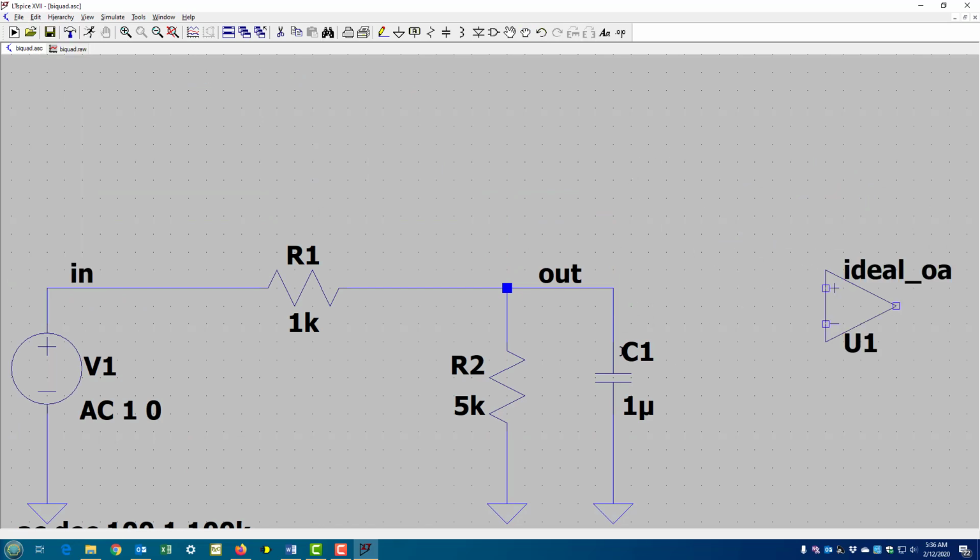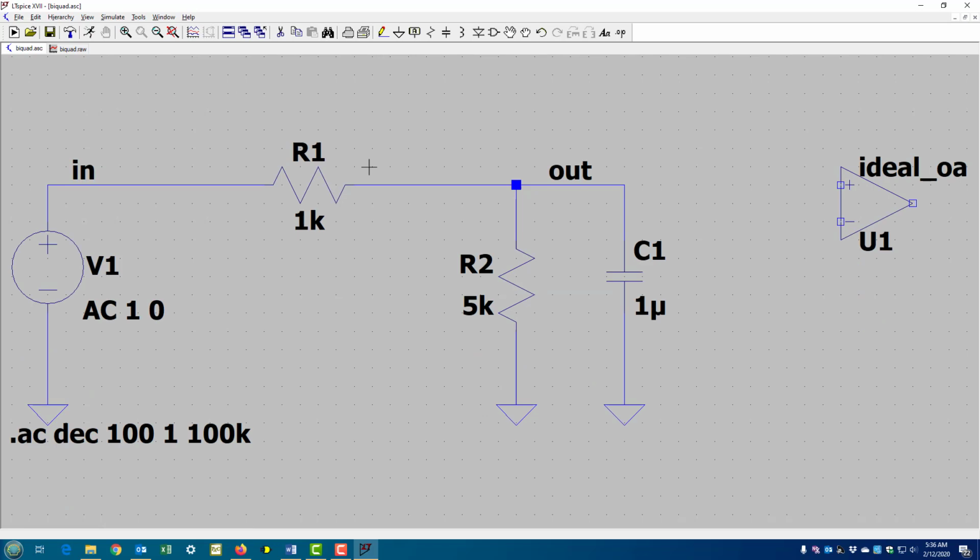If you do move and you look in, now you see they're actually active. So to use Control R and Control E to get your components into the right position, you have to go to the move or the drag mode. What's the difference between move and drag? If you say move, you can move a component and take it out of its location. If you say drag, it'll stretch the wires. That's the difference in the schematic. When it's open like this, it doesn't really matter.